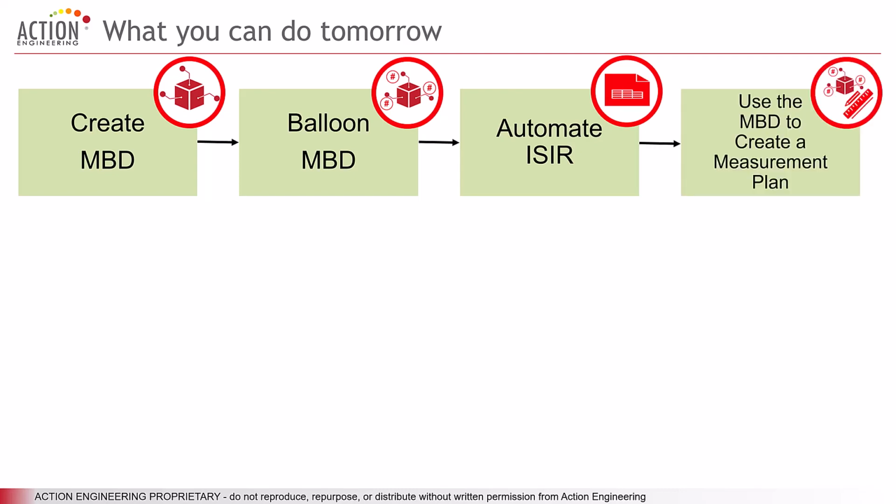Then the MBD is imported into digital metrology planning software. Today we're going to see Calypso from Zeiss, where the user of the software does not enter any data. Rather, he just imports it. During this step, they identify that the GD&T is best validated using a CMM and an X-ray device to check the overall profile tolerance on the cast surfaces.